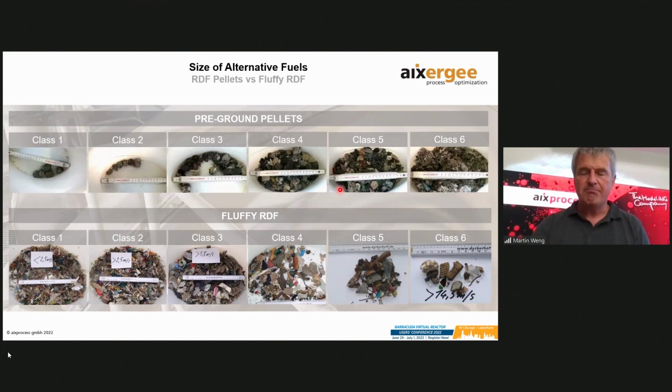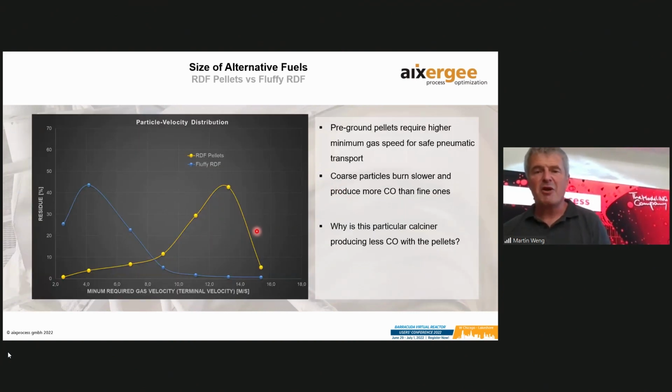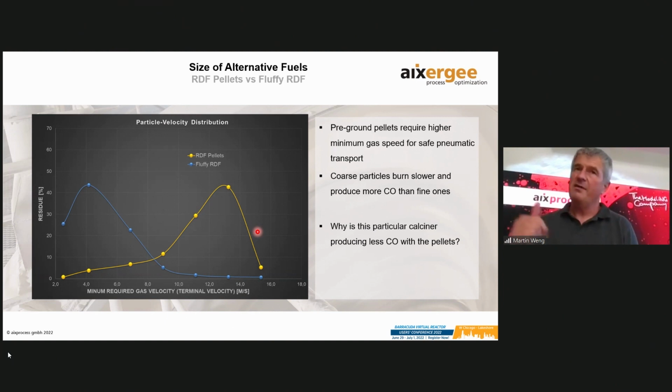Yeah, I didn't really mention Barracuda yet, because for us it's more than natural to do these simulations in Barracuda. The reason being, although the average particle concentration in this entrained flow reactor is something about 1 kilogram solids per kilogram gas, particularly at the meal input and the fuel inputs, we have a real dense flow, leading to typical clusters of particles, typical transient behavior, as you will see in a minute.